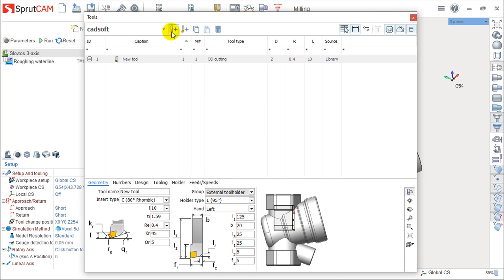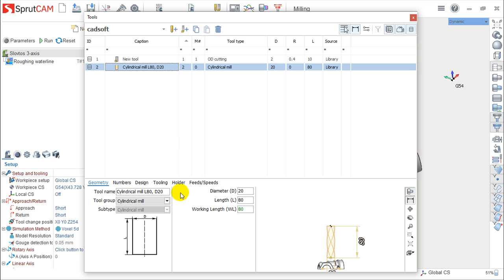Under each one of these, we click it and we need to define the tool name, the shape, which is linked to the tool group, and the dimensions, and we have these letters, this legend here, which connects to each dimension. Numbers on the magazines, correction factors for length and for radius. Design, so if it is inches or millimeters. Number of teeth, plunge angle, durability, because we can also have this factor in our CNC file to make automatic change of tools.